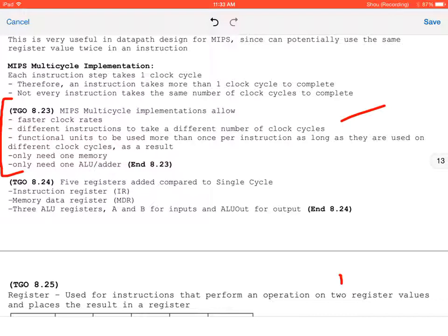If I'm trying to determine the ALU source, and I name the control signal ALU source, right? Like, if I want to determine if I want to read from the memory, the signal is called memread. If I want to write to the data memory, I call it memwrite. If I'm trying to determine if something's coming from the memory to the register, I call it memory to register. So I have a new thing that I want to define, whether it's going to be called instruction or data. What do I want to call that control signal?